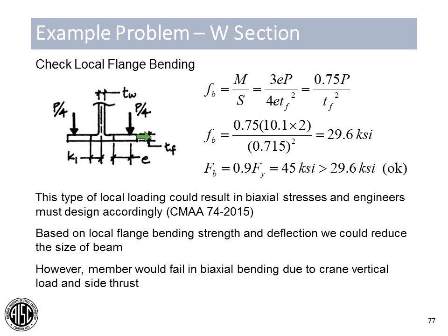The reason being, as this force moves closer to the heel or to the fillet of this member, the effective area reduces by the same amount. The effective bending area reduces by the same ratio. So it doesn't actually matter in these combined cases where you apply that force along the flange length or width.